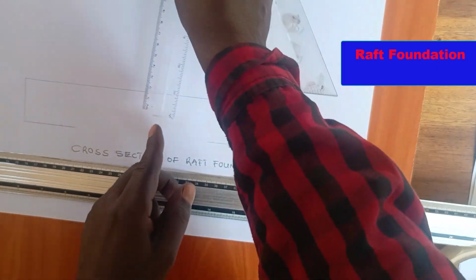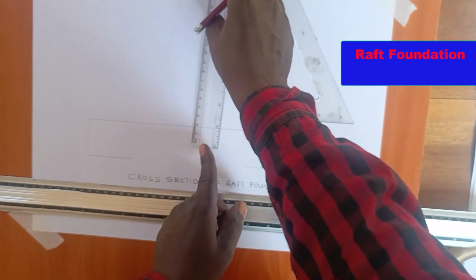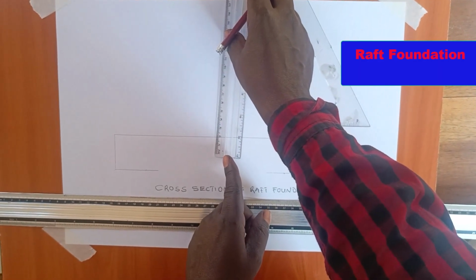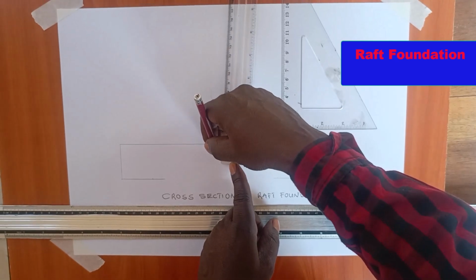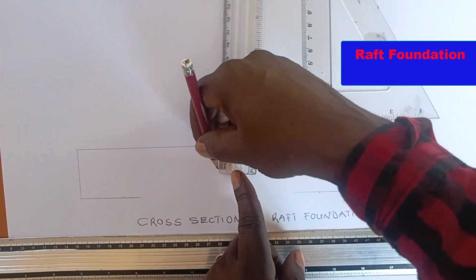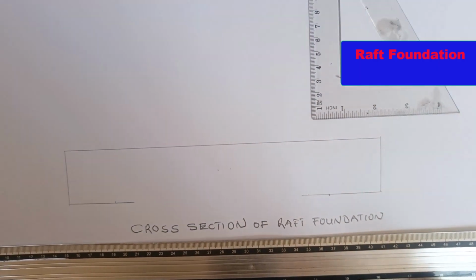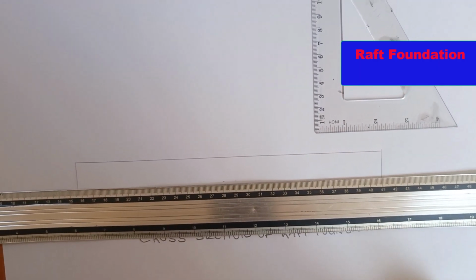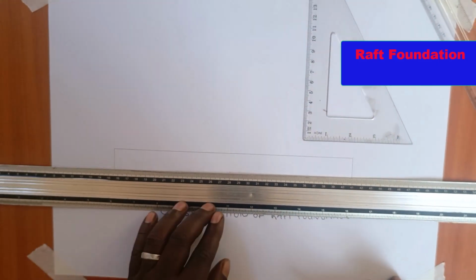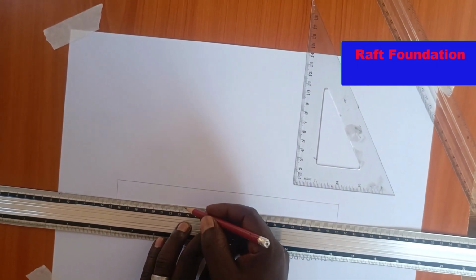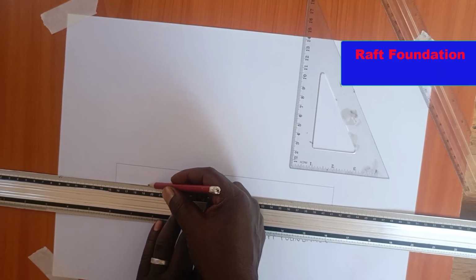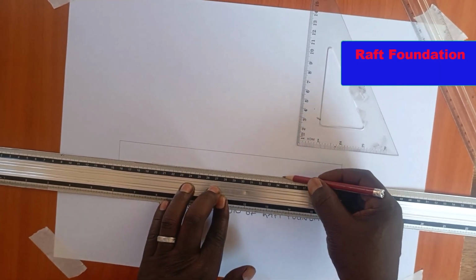And the depth of the concrete from the middle part here is 200 millimeter. So I can also measure 200 millimeter here. I mark 200 millimeter. I mark. So now I'm going to make a line here showing the thickness of our concrete in the middle. Let me first make a construction line, very faint line.